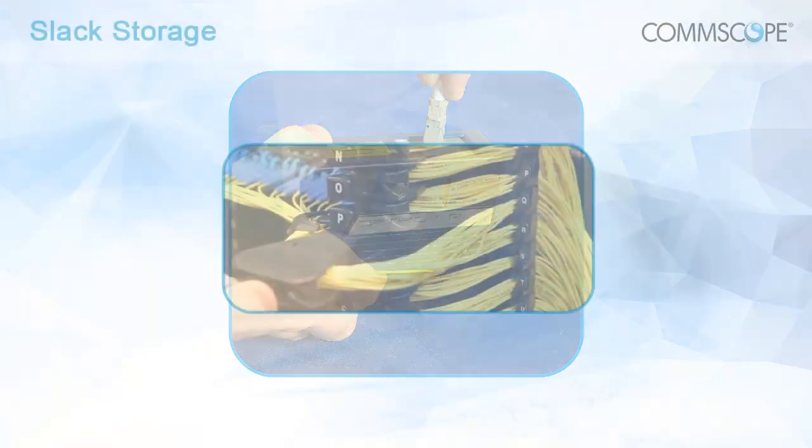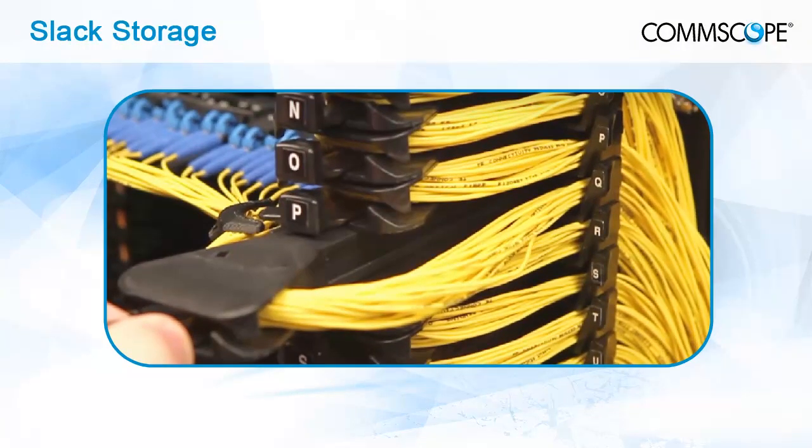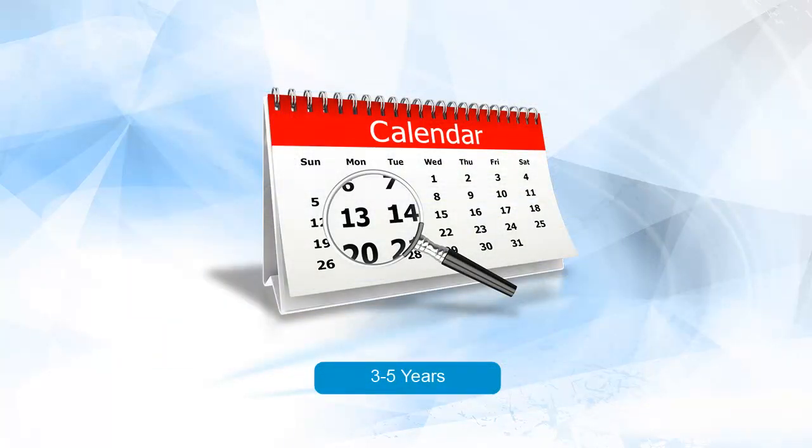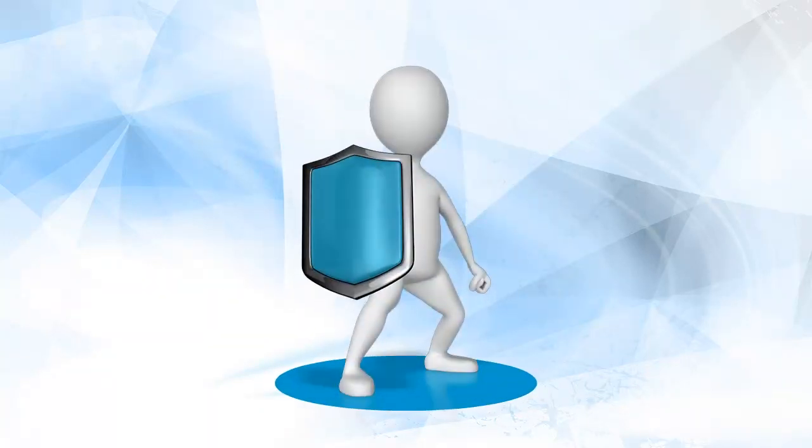Most ODF systems encounter cable management problems in the storage of excess fiber cable. Since most single-mode connectors today are still factory terminated to a patch cord of a predetermined length, there is always some excess fiber remaining after the connections have been made. At some point during the life of the fiber network, it is likely that virtually every fiber circuit will be reconfigured. For most circuits, the duration between reconfigurations will be long, perhaps 3 to 5 years. During this time, these fibers need to be properly protected to ensure they are not damaged during day-to-day network operations.